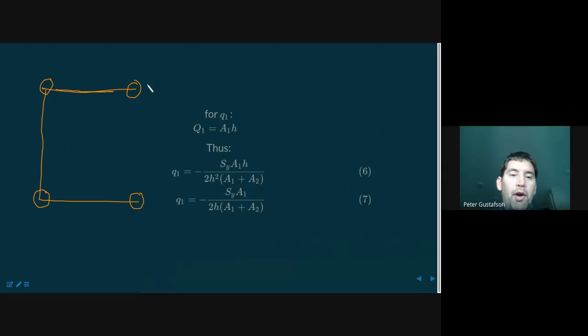We start our S-coordinate system over here going inwards, and we start counting I's. So, out here there's no shear flow, it's traction free. We step through that first segment. We have now a constant shear flow that I'm going to call Q1. And Q1 is the sum of all of those flows, right?